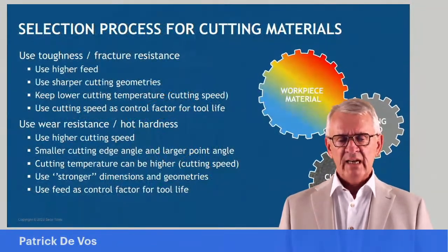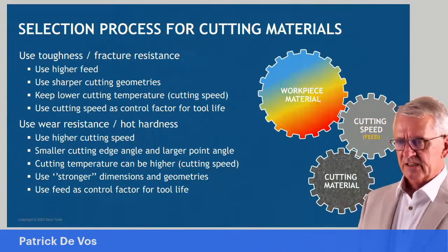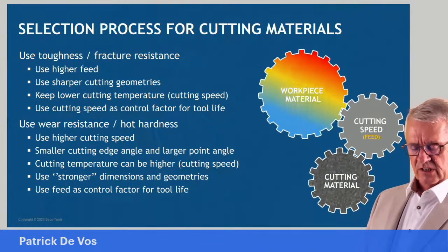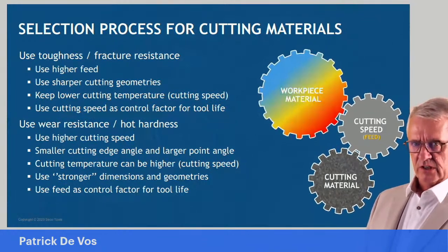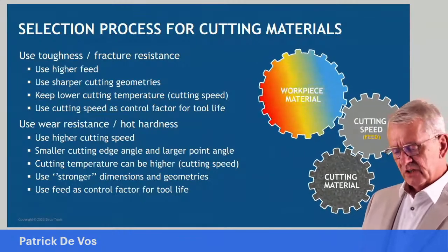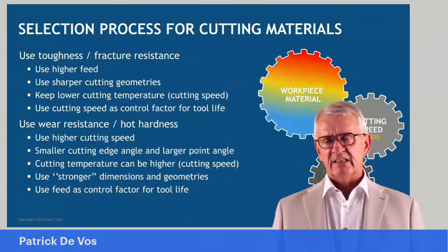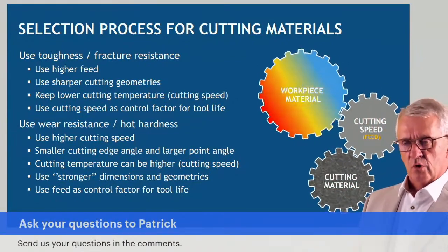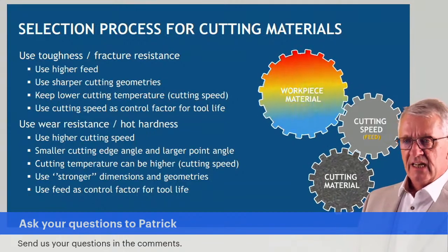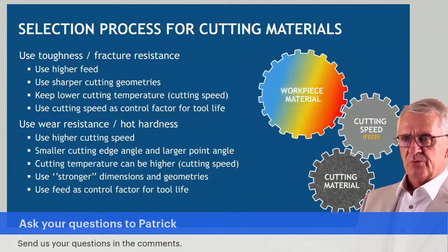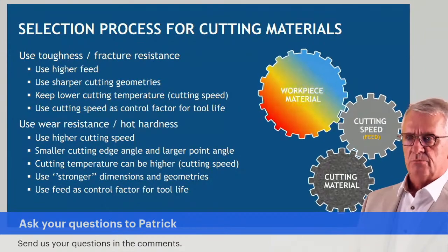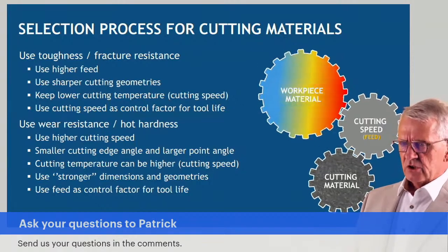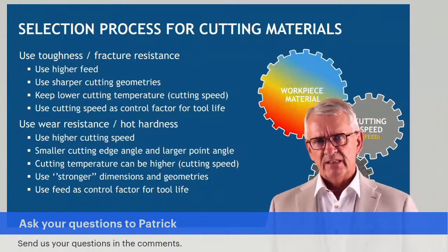And of course, what I already said before is, whatever cutting material you select or decide could most probably be the best choice in your application, a selection of a cutting material is not an island. It does not stand alone. It is connected to workpiece material properties, and the linking between workpiece and cutting material is mainly the cutting speed. To some extent, in some applications, also the feed plays a role.